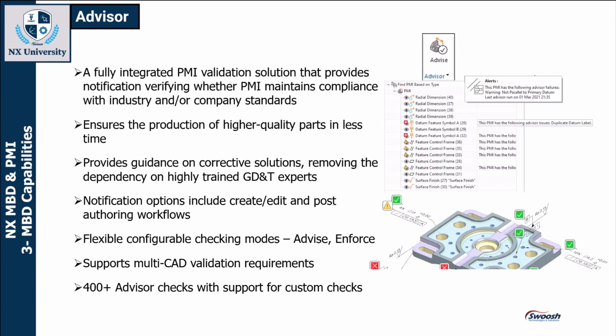So if you have somebody that's new to the GD&T process, applying GD&T to parts, this PMI Advisor can help those new users to learn how to apply PMI to features and do that in the correct manner here. You're going to see in the demonstration, when you do apply PMI to the part and then run the advisor, it's checking to the standard that you prescribed or told the software you're designing the product to, and it's going to start to flag the PMI with a green check mark, a yellow triangle with an exclamation point, or you'll see a red X on some of those features if they're out of compliance.